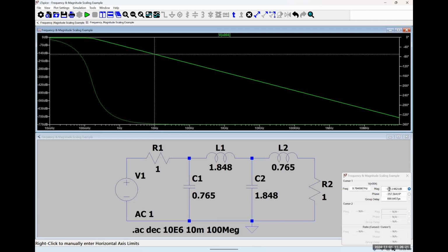So what's that change? -80 decibels per decade. Does that make sense with a 4th order filter? Absolutely. Every order is an increase of -20 dB per decade, just like we've seen previously in the class. So we have a system effectively where, using our filter tables and stuff like that, we are told how to get a 4-time repeated pole effectively at a particular frequency. Okay.